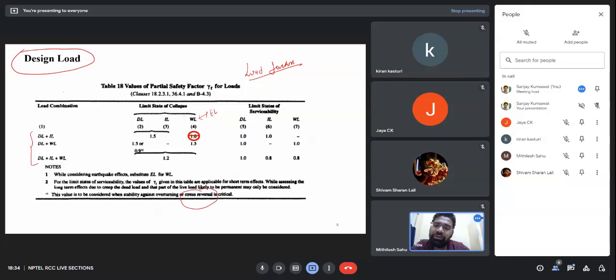During load reversal, at the time of earthquake loads or wind load, we can have a negative impact of the dead load, and that is the reason the effect of dead load may be neglected during such load reversal. What we assume is the beneficial effect of dead load, but that beneficial effect may not be available during the stress reversal phenomena which go on in the structure during activities such as wind loads or seismic activities. So basically these all were load factors for limit state of collapse.